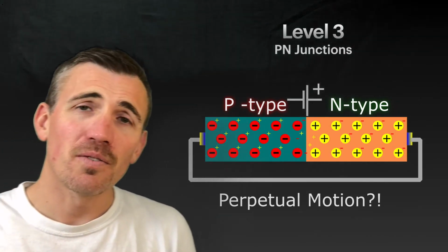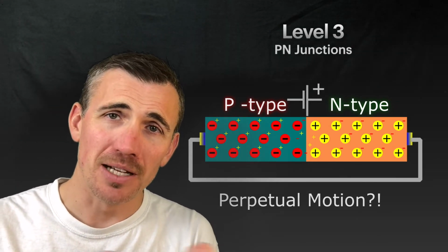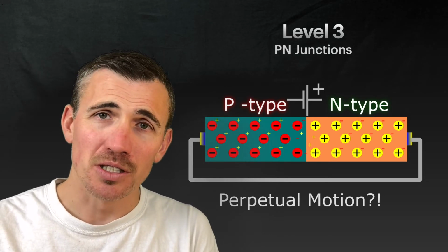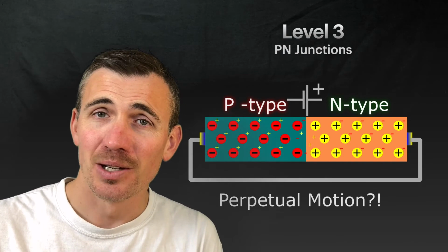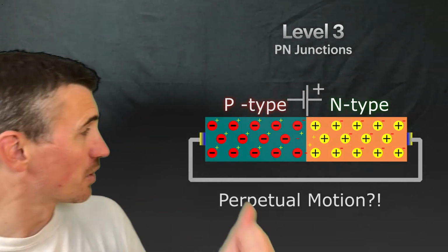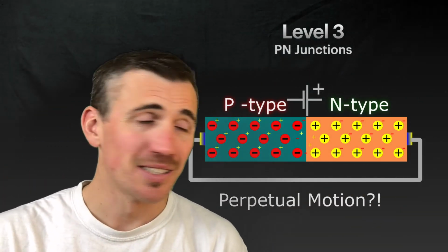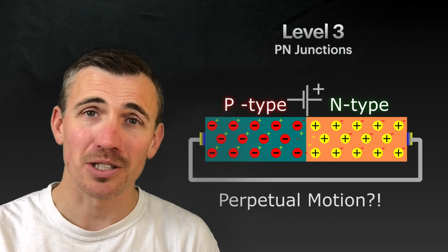Because you can form a p-n junction between a p-type and an n-type, but by the same arguments you can also form a junction from an n-type and a conductor, or a p-type and a conductor. And it turns out that we've just formed two such junctions wherever we've hooked up the wires.